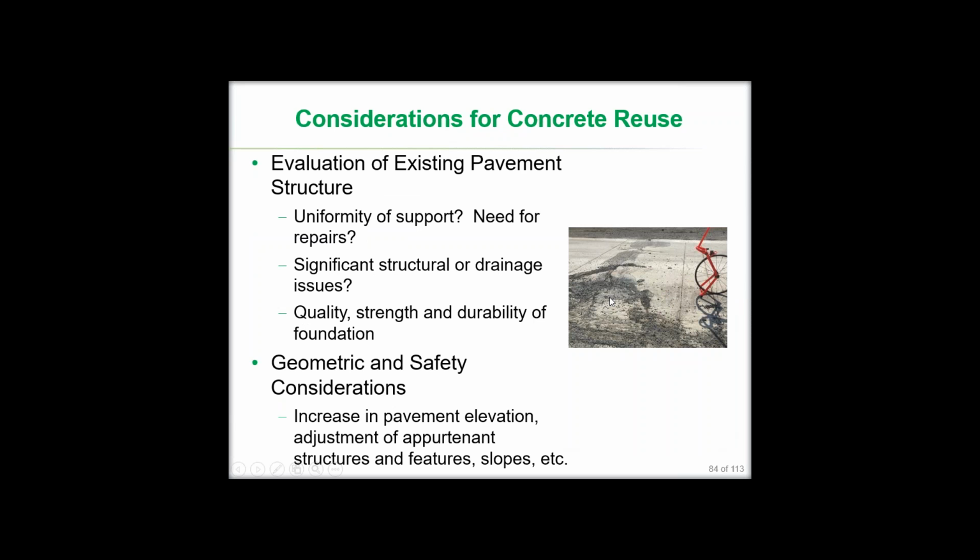Here's an example of a blow-up on another concrete pavement. This is one that actually was being reused in place. Again, this is right near my house, PA 50 here in Pennsylvania, and it's an area where there was a little bit of a blow-up there in that one area, and you can see they've already cut that and they're doing some replacement on that to restore that area locally before placing an unbonded concrete overlay. So reusing the existing pavement with a bit of repair.